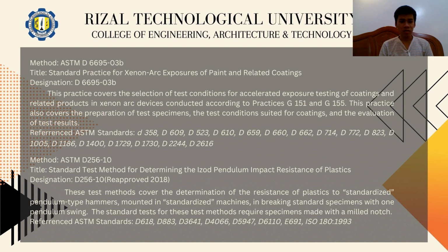Next is ASTM D256-10, Standard Test Method for Determining the Izod Pendulum Impact Resistance of Plastics. These test methods cover the determination of the resistance of plastic to standardized pendulum-type hammers mounted in standardized machines in breaking standard specimens with one pendulum swing. The standard test for these test methods requires specimens made with a milled notch.